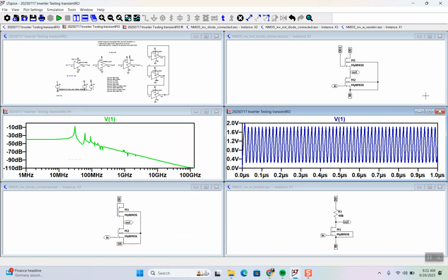Now we should have hand calculations for that. That I should say are conflicting. Conflicting requirements. And so, you know, you would use LTspice to verify that things will still work. You can't hit every spec, but you might have to change your spec to a speed of less than this is okay. As long as the speed is faster than this, and the logic level low is lower than this, logic level high is higher than that, right?